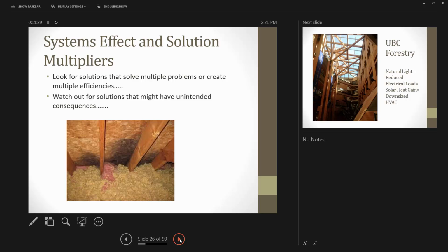Where it really starts to make sense is when we're not talking about a 1,700 square foot house, but when we're talking about a 150,000 square foot commercial building. If you can spend a percentage to increase your thermal envelope, reduce not only the size of the heating system that you need, but you can reduce the size of your air handling and your ventilation. You can reduce the size of all of the thermal delivery in the building, and then recognize that savings year over year.